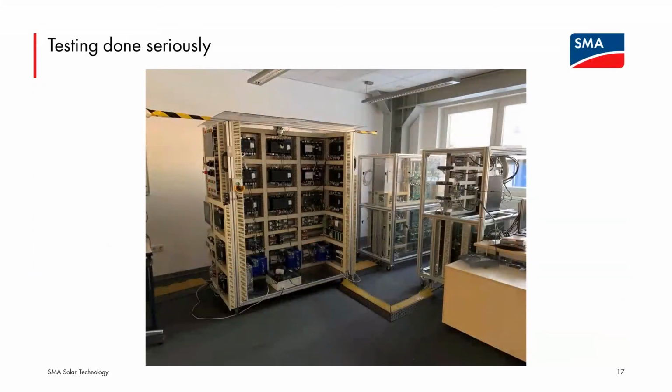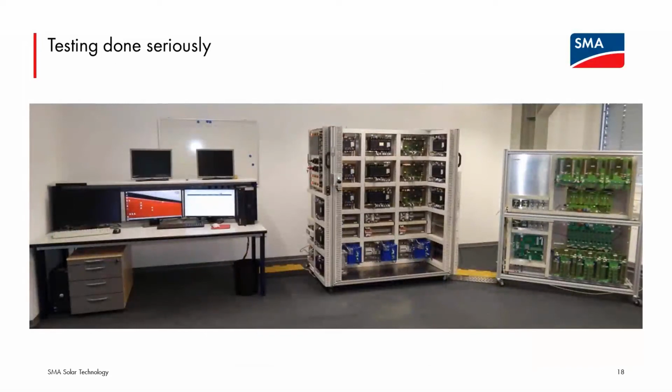So as we can see, a lot of equipment is involved in testing the inverters, but not all tests require the presence of the full hardware. Many tests cover software and control-related topics. That's why we are also running hardware-in-the-loop systems that involve our control boards running the real control software. The heavy hardware and surrounding environment like DC sources, the AC grid, and everything in the powertrain of an inverter is emulated by a simulation system that stimulates our control boards.